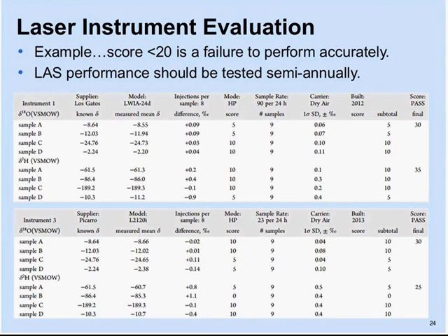And again, what's of primary interest is the third and fourth columns for both. You can see the measured value, and by measured here, I mean the value that has been obtained using the instrument, your calibration standards from the first table that I showed you, and the normalized results relative to VSMOW-SLAP, and then compare that to the known value, and then look at the differences. So this seems to be quite a robust way to evaluate our laser instruments, and it probably would apply equally well to IRMS.